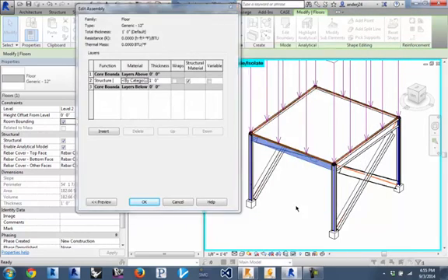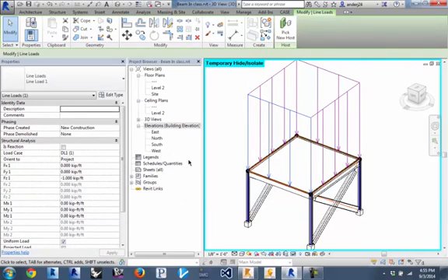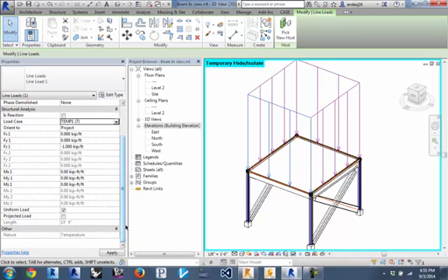The other way to do it would be to put your composite deck on there and then create two dead loads, one dead load being your material assemblies, like your carpet or your tile or whatever, and then the other dead load being the design dead load, right? Typically that's driven by program. Every program will have a different design dead load that you have to accommodate for, and then a different live load, right? So a library has a different dead load profile than, you guys probably already know this, right? Than an office building. And that's all driven by code. But this other dead load that I'm talking about is more the actual weight of the building products, the assembly that you're going to be putting into the building, which wouldn't be accounted for in those design dead loads. Right.